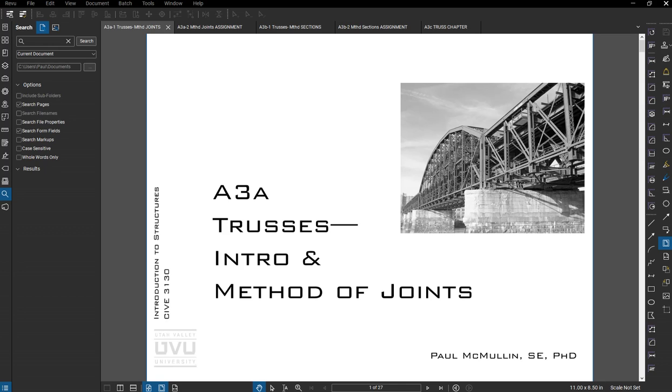All right, folks, let's jump into trusses here. This is something we talked about in statics, but can certainly expand on substantially here in this class. Trusses are the most efficient structural element, mainly because they're so deep or tall that the effective moment of inertia is very, very large. So that's why they're used. It really provides the least material for a given span.